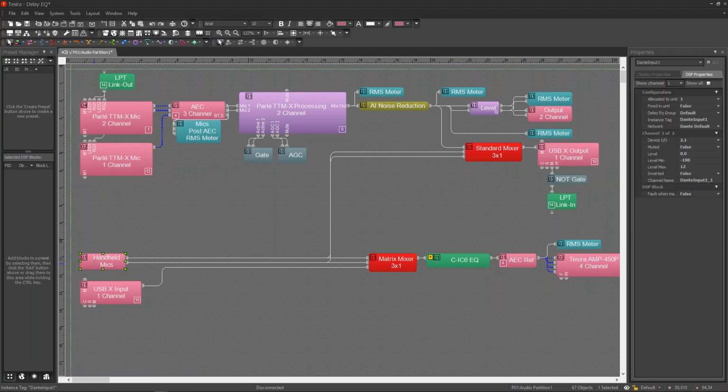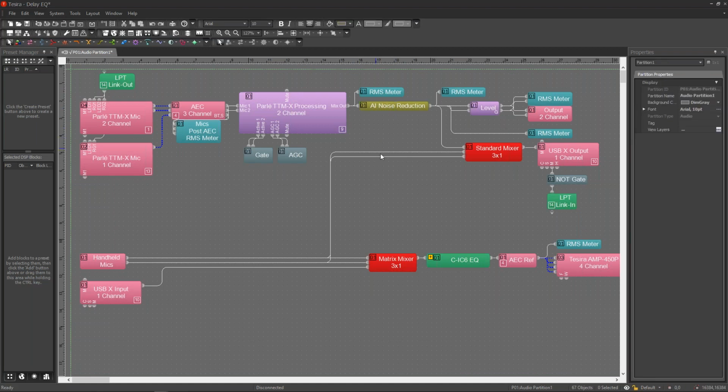But we've also got some handheld mics, and these are going to be used for two purposes. So they will be sent to the far end. If you're talking on a handheld, the far end still want to be able to hear you. But we need local reinforcement into this system. So these handheld mics are also being routed to the local amplifier so that the audience can hear themselves. Now, when we considered the 50 milliseconds of delay this is going to add, that could be problematic.